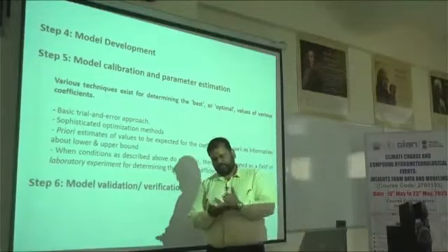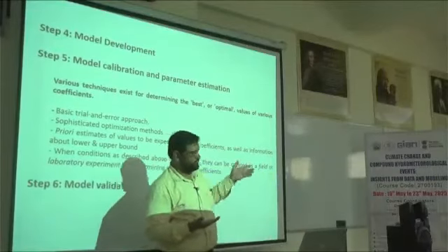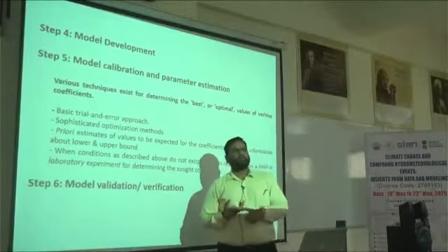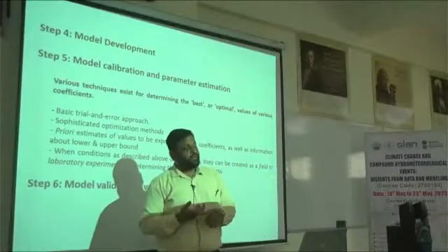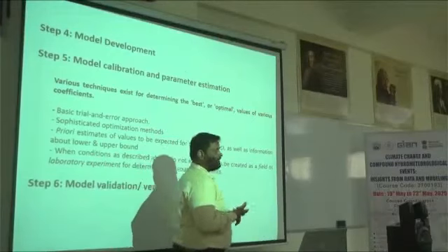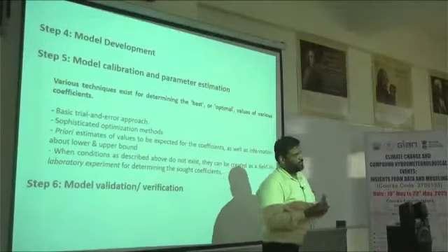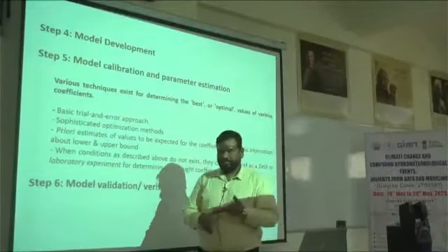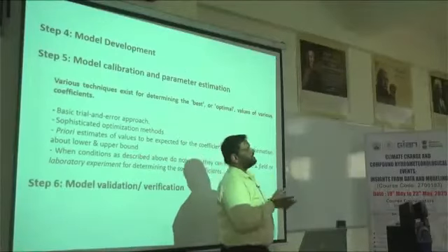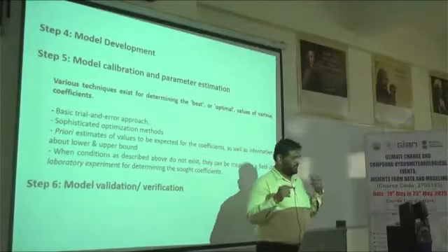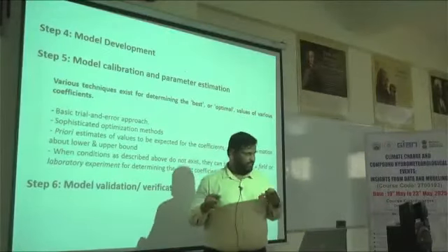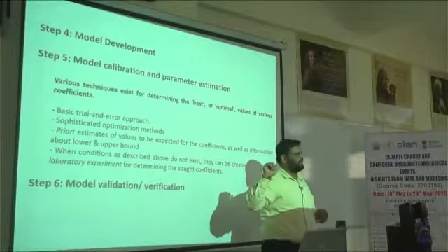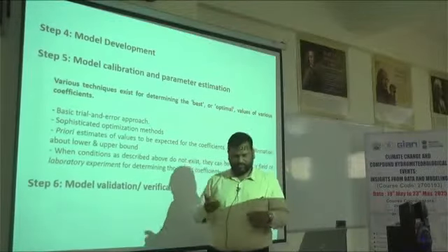Then if you talk about evaporation equations, there are 3 equations in the SWAT model also. You might have heard about the Penman-Monteith equation. That Penman-Monteith equation requires a huge amount of data. Every climatic data you have heard about would be used in Penman-Monteith, like solar radiation, wind speed, relative humidity, everything is required. So it's a very complicated equation, we can say. Then the second is the Priestley-Taylor equation. Some parameters have been omitted from that equation, so fewer parameters are required for Priestley-Taylor.